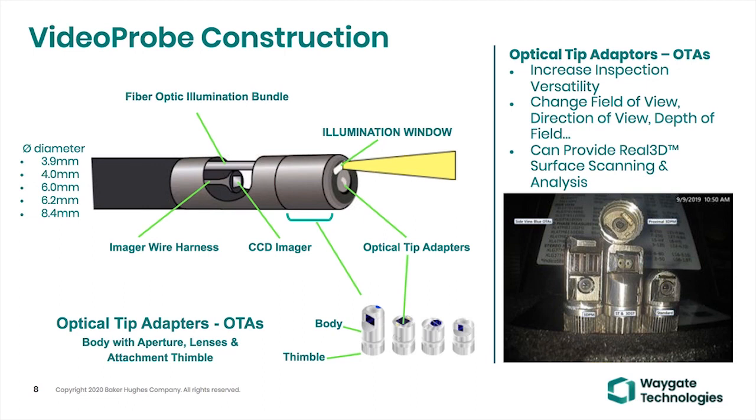But if you look at the picture of the lenslet laying on its side, there's a white bar up at about 2 and 3 o'clock. That little white bar is holding micro pins, pogo pins, if you will, to provide power to those 3D phase generators. And then just outside around the perimeter, you see the threads that are holding that optical tip adapter onto the camera. So we're talking about lenses in some cases that have an OD of 4 millimeters or 3.9 millimeters. So cleaning them is paramount and taking care of them properly.